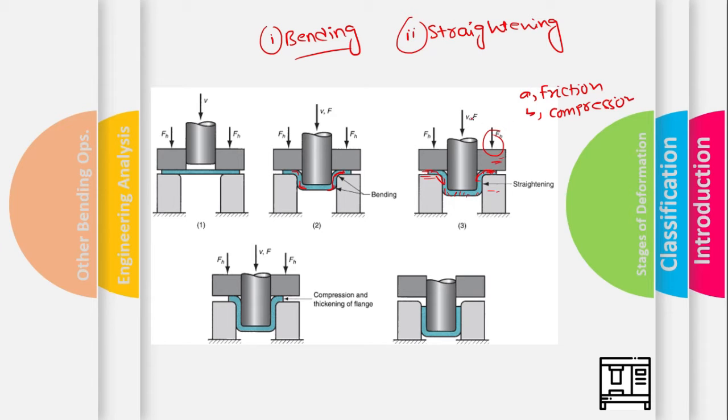The second factor, compression, is also occurring in the outer edge of the blank. As the metal in this portion of the blank is drawn toward the center, the outer perimeter becomes smaller. Why is that? Because when the metal is rapidly moving in towards the die opening, the outer perimeter becomes smaller.